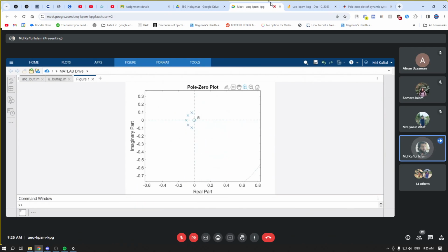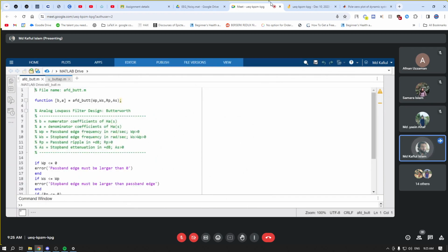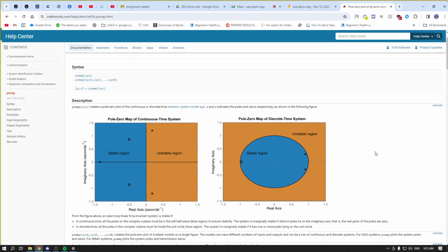So all the poles, there are 5 poles, right? All of them seem to be on the left hand plane, which is good. But how about the other poles? It's supposed to have 2n minus 1, 0 to 9, so it's supposed to have 10 poles. It only shows the 5 left hand plane poles. Okay, so it is not working. We do not know. It seems that apparently it is stable because it only plots the left hand plane poles.